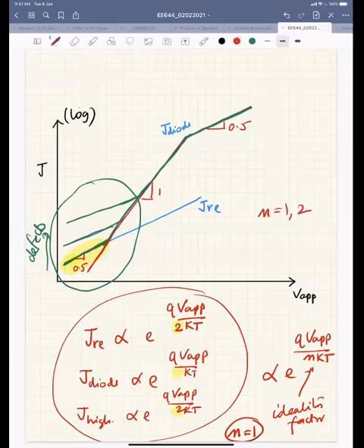For the silicon case, we actually observed this recombination part. That's the reason we tell the ideality factor for silicon will be somewhere between 1 and 2, right? And somebody told, okay, let's put it as 1.5. That's why I read in the books that your diode current is e to the power qV by nkT and n is equal to 1.5 for silicon, right?